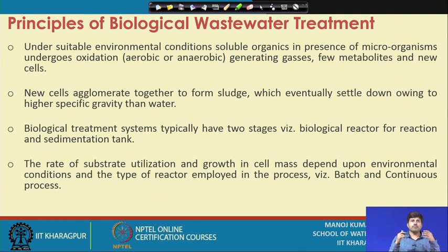Now, under suitable environmental conditions, the soluble organics in the presence of microorganisms undergo oxidation. This could be aerobic or anaerobic, and generate gases, a few metabolites and new cells. This is typically what happens in biological wastewater treatment systems.